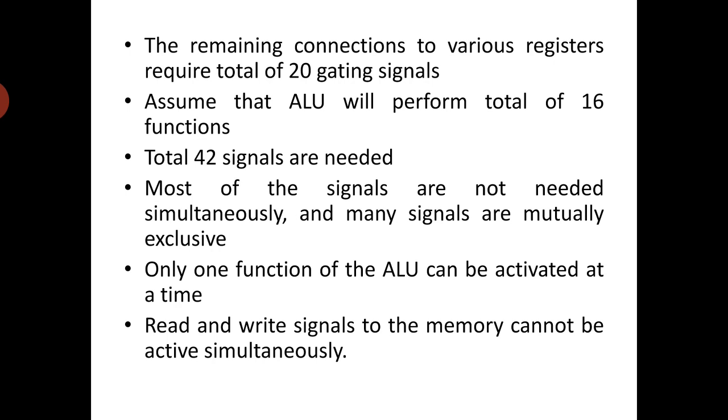And also read and write signals to the memory can't be activated simultaneously. So these are some examples: the ALU will perform only one function at a time, only one register can transfer data onto the bus at a time, and only one of the memory read and write signals will be activated at a time.